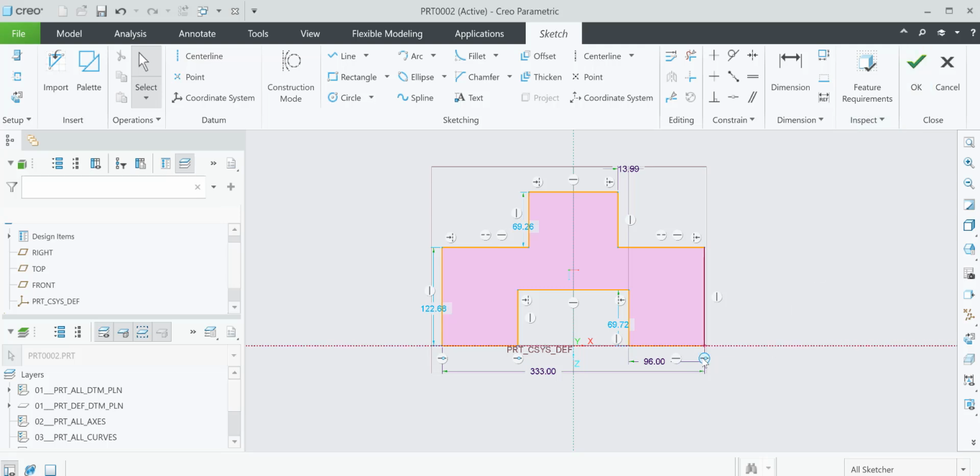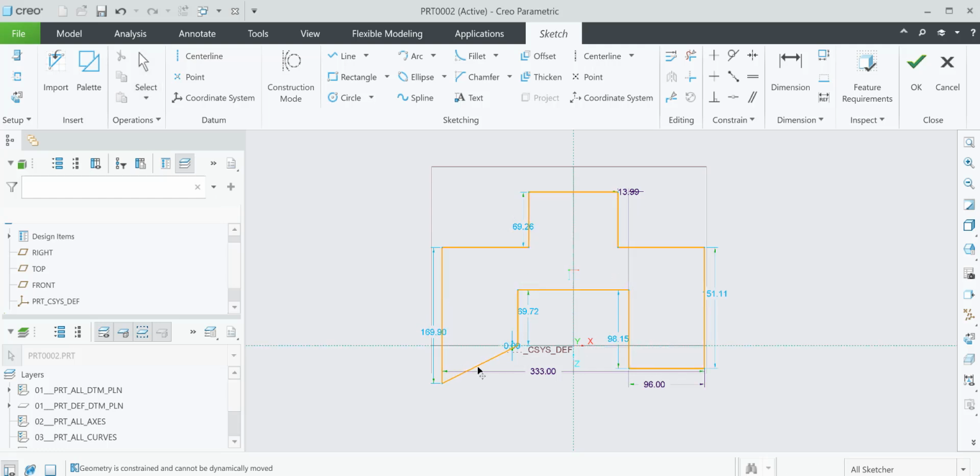Let's notice this coincident constraint here at the end. If I delete that constraint, I can change the geometry. I tend to encourage young designers to think more in terms of making these planes relative to how the geometry is used in the assembly.